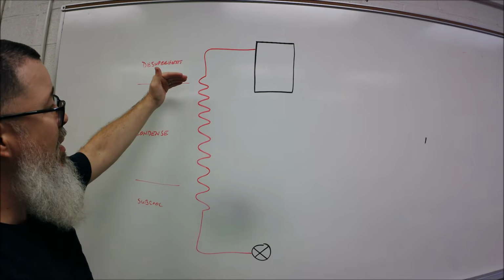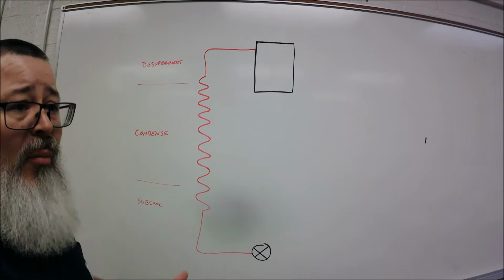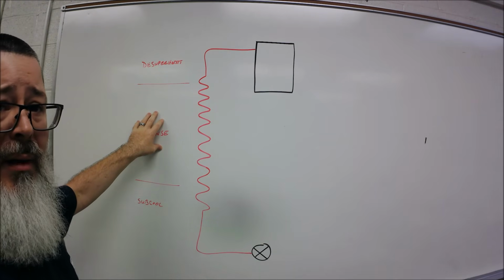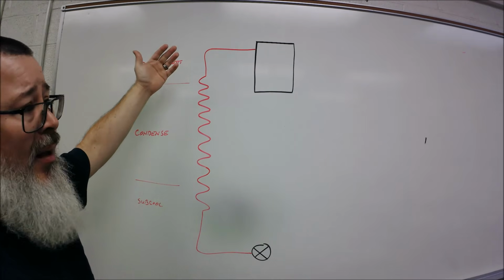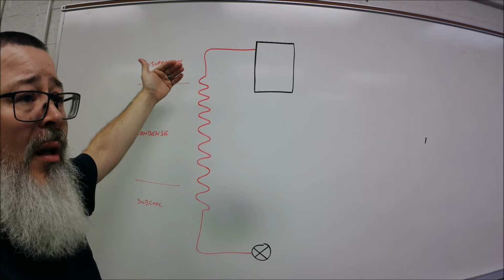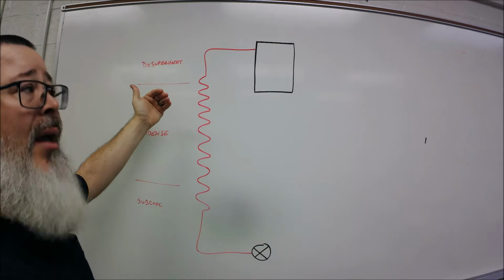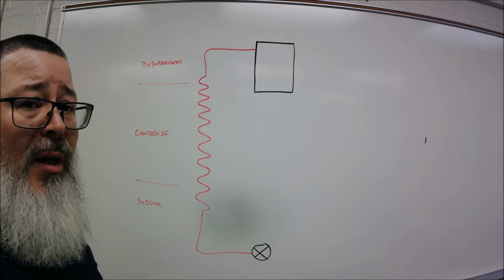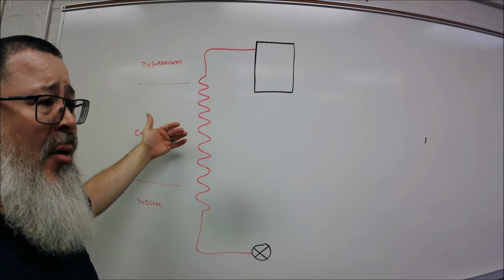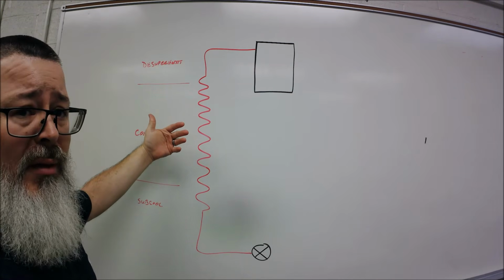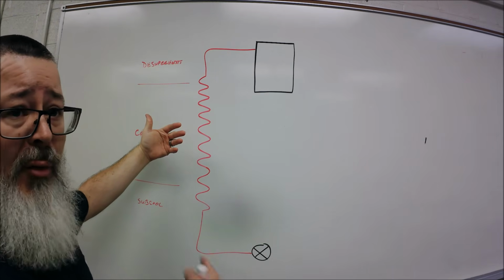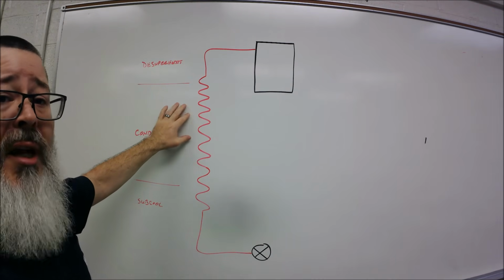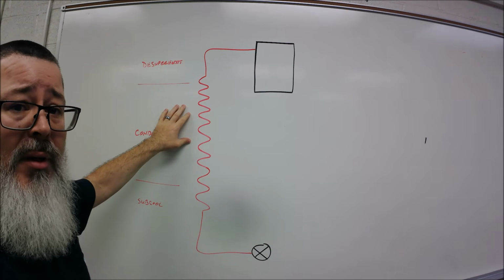All right. So it's a latent process for the bulk of the work that we want to do, and we condense. So we're going to take that, like I said, 140 degree superheated vapor coming in from the compressor and the evaporator, and we're going to initially reject a lot of sensible heat. Once we get down to that 105 degree saturation point at that pressure, 340 or so in this example, then we're going to do our change of state at the 105 degree saturation point.